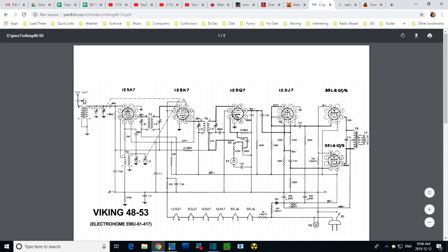So maybe there's something going on between the antenna and this coil. I doubt that. The antenna is uncontrolled. The amount of wire attached to the radio is uncontrolled. So would the radio designer attempt to resonate the antenna wire in this coil against this capacitor? I kind of doubt it. I think this capacitor is in there more for safety reasons. A very, very small capacitor. But I don't know why it's there for sure.